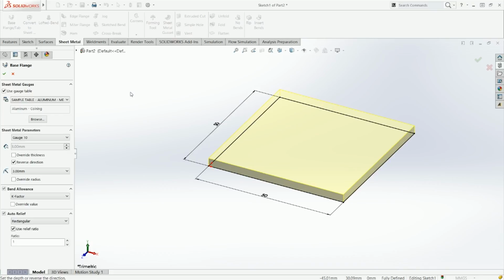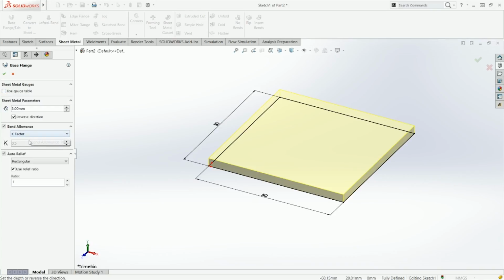And that's why you usually use a gauge table, just because you can define various K factors which relate the thickness of the material and the radius of the bend, which is also done in a press machine or stuff like that. That's why you usually have to use gauge tables. If you don't use gauge tables, you can define a K factor. The bad thing about that is that whenever you change your angle or your bend radius, the K factor changes for the same material.